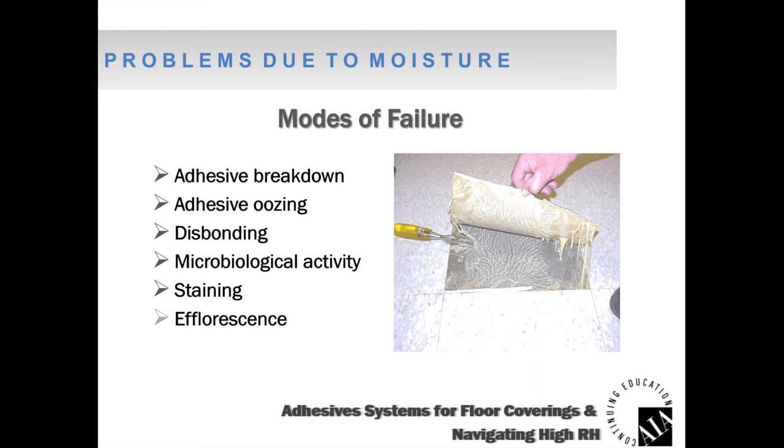If you have adhesive that's emulsified, certainly the adhesive can start oozing. It certainly equates to disbonding. If you got liquefied adhesive underneath the floor covering, it could cause microbiological activity. It's a big fancy word for bugs underneath your flooring, things that are growing.